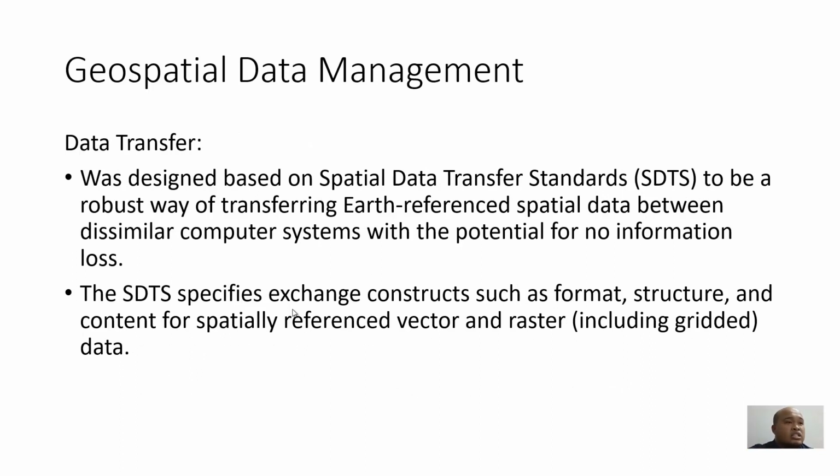And the third one is data transfer. Data transfer was designed based on the Spatial Data Transfer Standards (SDTS) to be a robust way of transferring Earth-referenced spatial data between dissimilar computer systems with the potential for no information loss. The SDTS specifies exchange constructs such as formats, structure, and content for spatially referenced vector and raster data, including gridded data.